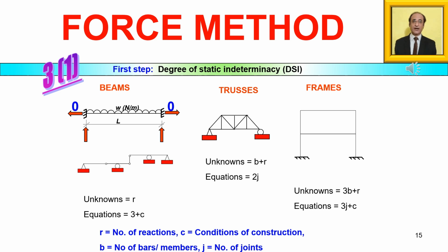The horizontal reactions at the supports are 0. Similarly, the values of the vertical reactions can be determined based on the symmetry and from the vertical equilibrium that both the vertical reactions shall be equal to WL by 2. Then, making use of the symmetry, the two unknown moments will be equal and opposite. So the degree of indeterminacy reduces to 1.